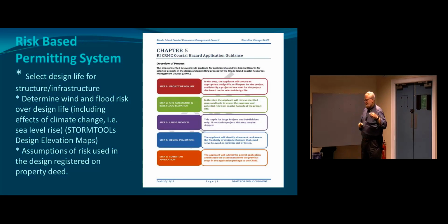I would tell you that the guiding underlying principle here in terms of decision making and permitting is what I call a risk-based permitting system. So in some permitting systems, one sets the standard and somebody else essentially has done the risk assessment, and the standard is set. We want to build there. Here's the standard. You build to the standard, right? So the problem now is that the conventional maps for flooding, as an example, where you would build to the standard, don't include sea level rise.